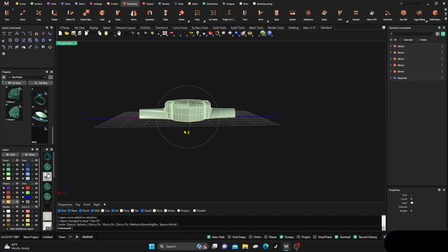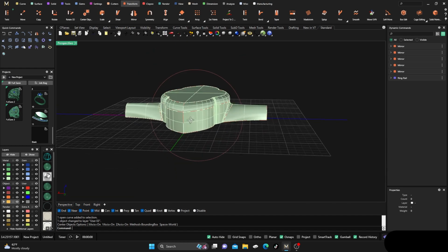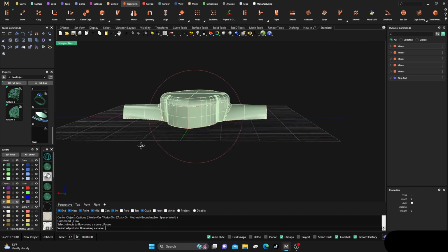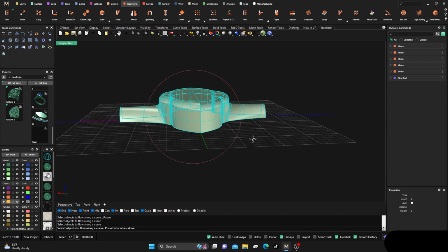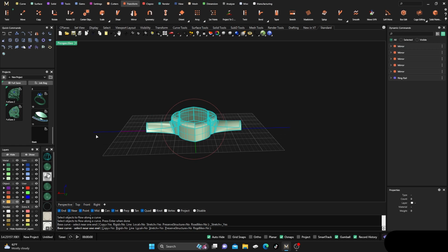Now what we're going to do is do a flow, right? We're just going to flow all this up here, even the curves. That's why we went ahead and did the curves, because it'll be easier for us later on. So we'll go to our transform, which we're already there. We'll go to flow, flow along curve, select objects to flow first, right? So we're going to select all those objects there, not our line or our ring rail, of course. And then we're going to hit enter, and then click on our straight line that has the same.